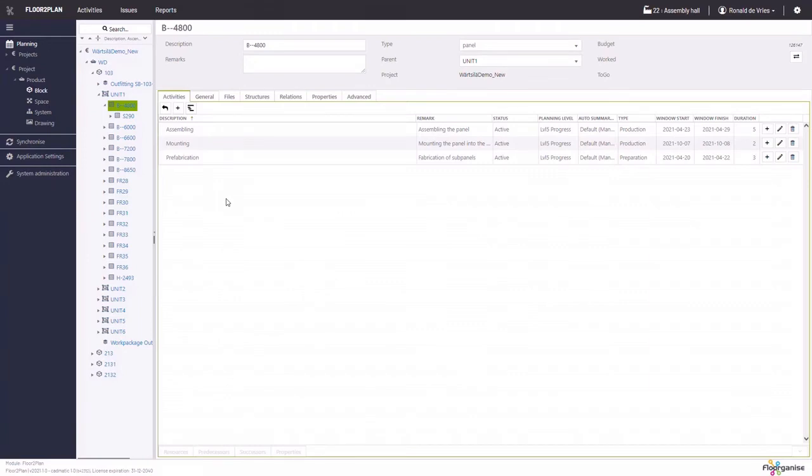Now, that whole hierarchy has been synchronized with flow to plan, so I see all that here for these particular individual items. And what we have now in flow to plan is a recognition of that whole product breakdown structure for that vessel, both on the end of the structural work as well as for the outfitting and the division into rooms, etc. But all individual parts are now recognized within their hierarchy, and for each of these parts we know what type of part it is or intermediary product it is, and we therefore can generate a train of activities for that particular item to be completed.